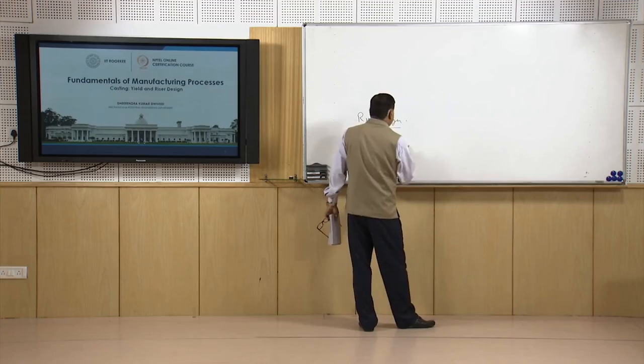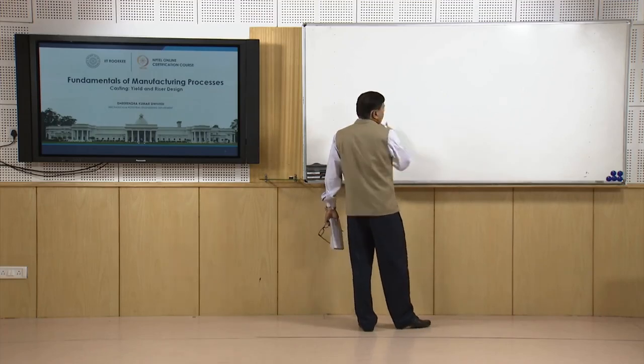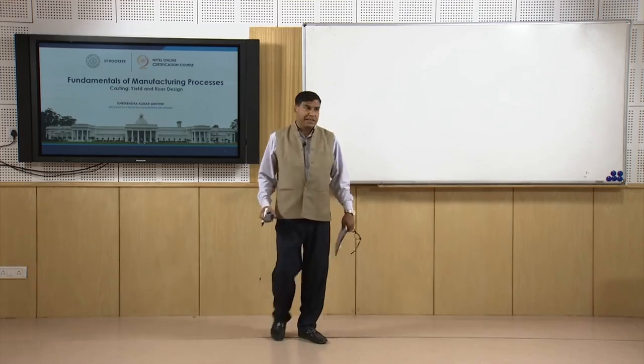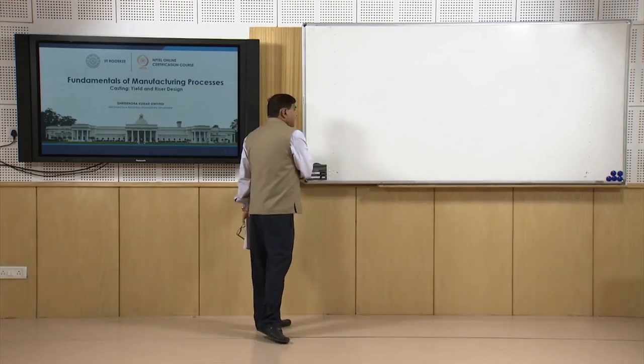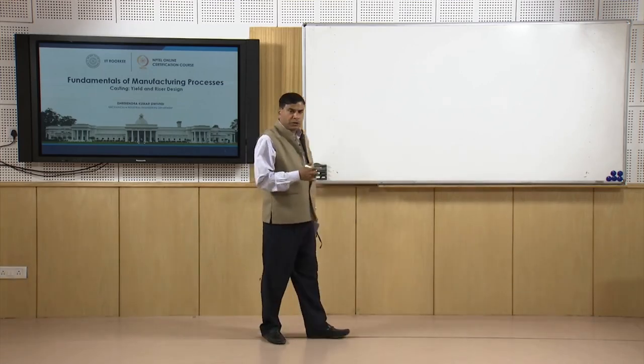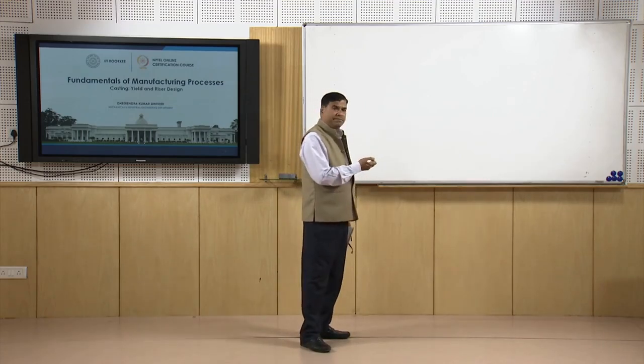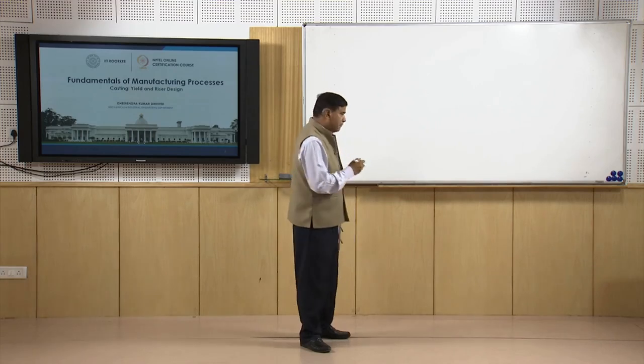So, if we see the role, for the riser to act effectively, the molten metal in the riser should solidify after the solidification of the main casting.